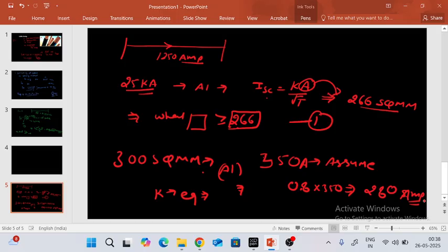So I have to use multiple runs. My requirement was 1250 amps, which should be carried by 280 amps per run. Dividing, it comes to around 5 runs. So I have to use 5 runs of the cable. That's clear from my side.